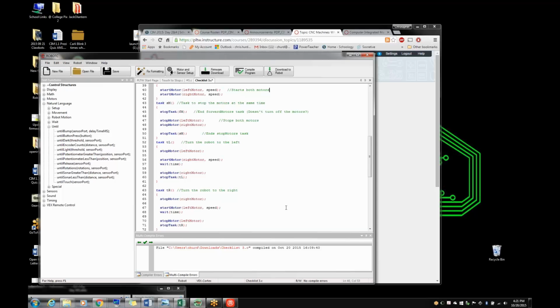And then we put a command in there that was, if the current light sensor value is greater than the stored value, store the new one, what you're reading now. And it just does this 360, finds the greatest one, and then they could do a while loop that said, okay, now run the motors in a circle while the light sensor is reading lower than the greatest value you found. Come around again, point right at that light sensor, and then the next thing was just go forward until the touch sensor hits the stand.